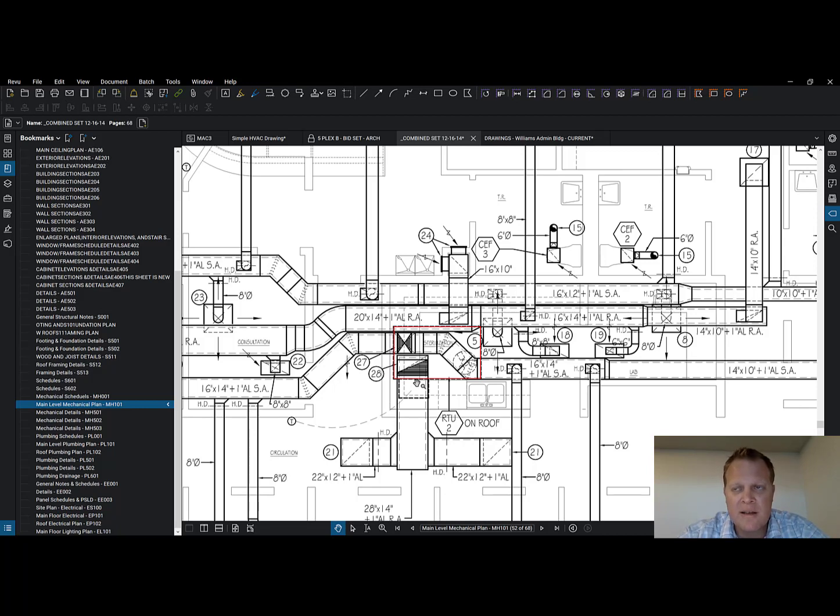Why don't we need, it has a cooling section and an evaporator section, so why don't we need a condensation drain? Well, it's up on the roof and there's already roof drains up there, so you can spill that condensate right on the roof, and the roof is designed to take water, so it can go right down the roof drain. It's not bad water or anything like that. It's just air that has vapor that's been cooled off and turned into liquid water condensate. So we don't need the sewer because it's not down in the basement like the residential one.